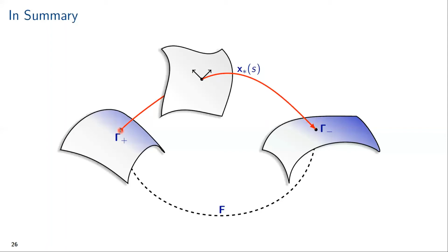Now we solved it by looking for a set of synchronization functions, which were described in terms of this variable motion generator S, which was sort of a reparameterization of time along the trajectory. This motion generator gives us an extra layer of flexibility when planning this problem, as in a sense we may let time vary along the nominal trajectory. This means that we can represent such a nominal solution with, for instance, polynomials of quite low order compared to if we tried to do the same with time, as we let the parameterizing variable s vary, its velocity varies along the nominal trajectory, giving us this extra layer of flexibility.